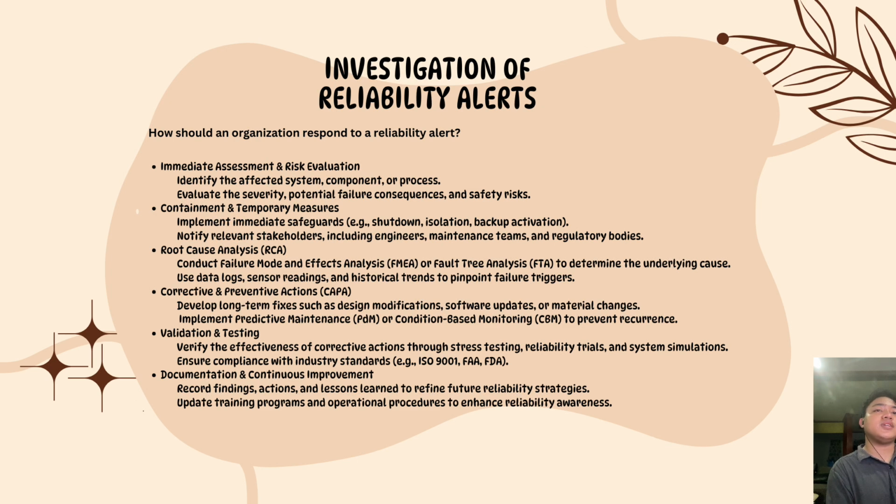Next is root cause analysis. Conduct failure mode and effects analysis or fault tree analysis to determine the underlying cause. Use data logs, sensor readings, and historical trends to pinpoint failure triggers. Next are corrective and preventive actions. Develop long-term fixes such as design modifications, software updates, or material changes. Implement predictive maintenance or condition-based monitoring to prevent recurrence.